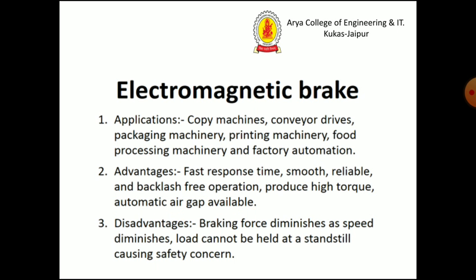Electromagnetic brakes are used in copy machines, conveyor drives, packaging machinery, printing machinery, food processing machinery, and factory automation, having fast response time, smooth, reliable operation, and so on, and having the drawbacks that the braking force diminishes as speed diminishes, and load cannot be held at a standstill, causing safety concerns.